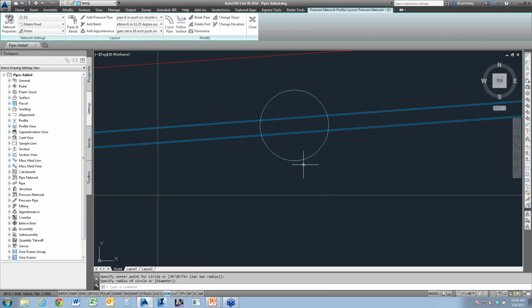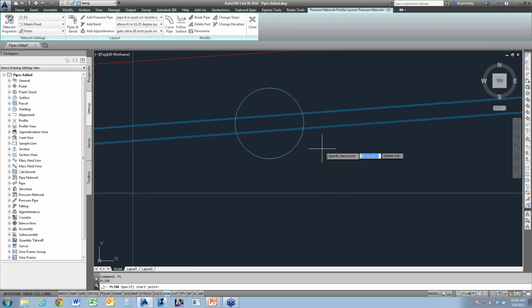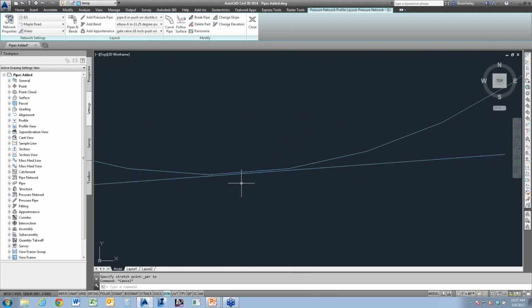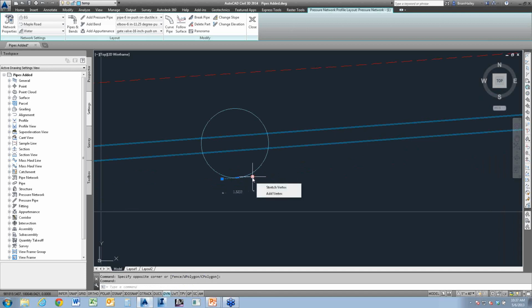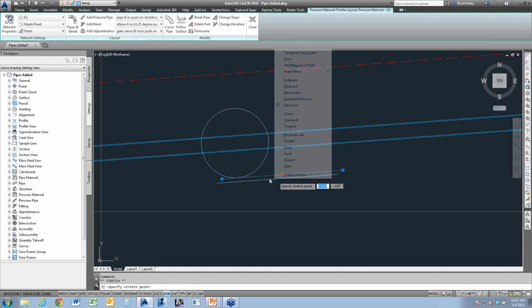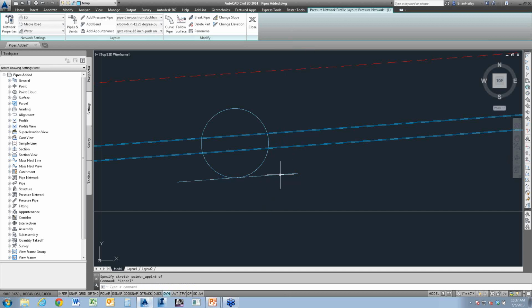So basically I'm going to draw in my crossing. I'm just going to draw a polyline from there to there. I'm going to go to the center, and we'll go perpendicular to there. So this is now tangent. And maybe lengthen this up a little bit here. That total length, 6 feet. Something along those lines. All right, I'll go ahead and copy this.